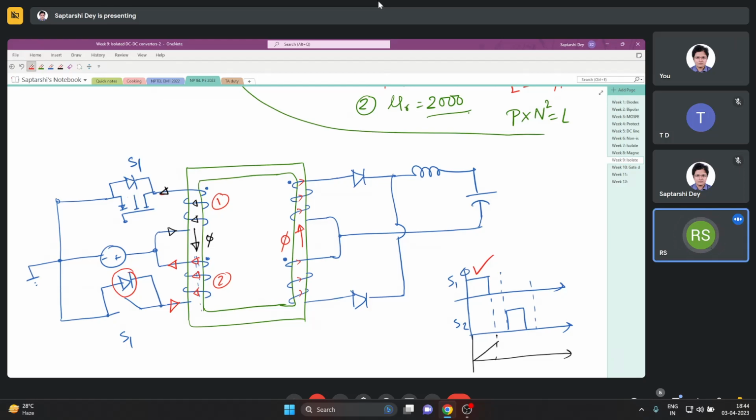Sir, when the flux in the core is flowing because of the current in a single winding, the currents in the other winding will try to keep the flux at the same value. Yes, Lenz's law. According to that, the currents in the windings will be induced. Yes, because the flux was trying to reduce, and Lenz's law said that the windings will try to oppose that.